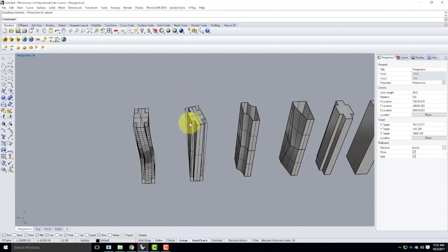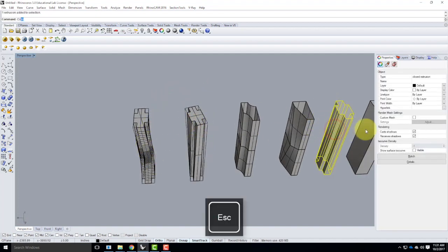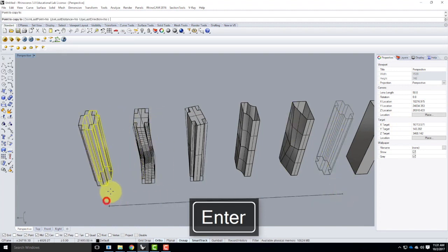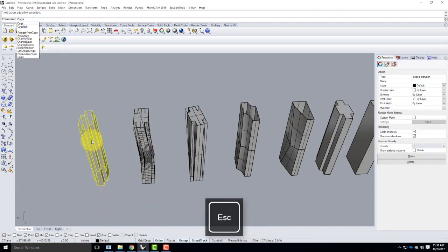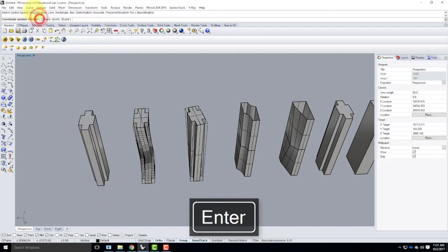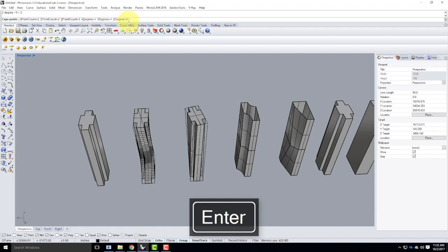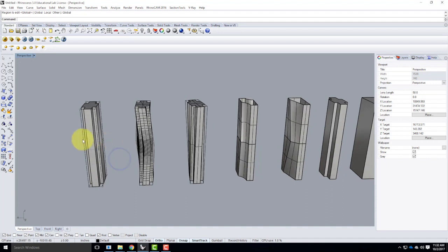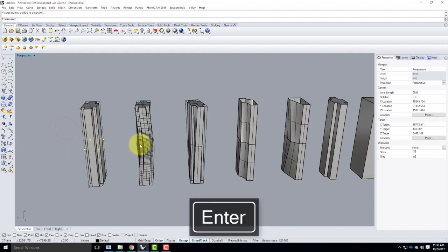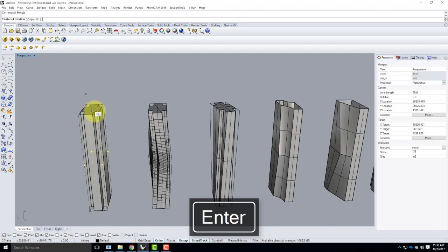So let's change it on the next one, same concept here, and we'll do it with a degree of 2. Bring that over, cage edit, bounding box, world. Okay, same z point count as 3, but our z degree is going to be 2. There we go. I'll go ahead and hit enter, global, perfect. So same thing. I need my little cheater, again, to know where that center is. Let me take these 4, and I'm going to rotate, exactly the same as last time, by 15 degrees.